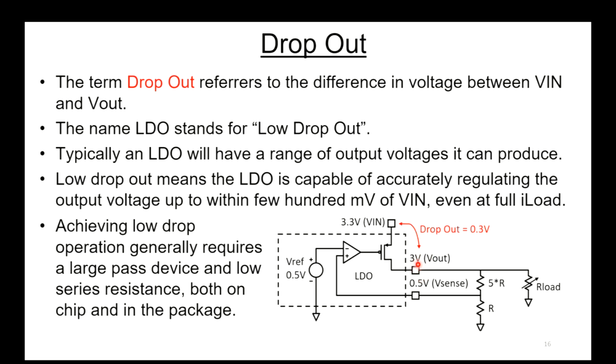Now you can see that achieving low dropout, especially when you're trying to pull a lot of current out of this device, can get kind of challenging because you have almost no voltage across this transistor. There's hardly any VDS. So it can get very challenging to get very low dropout. So marketing guys, keep it at 300 millivolts. None of this 100 millivolt stuff.